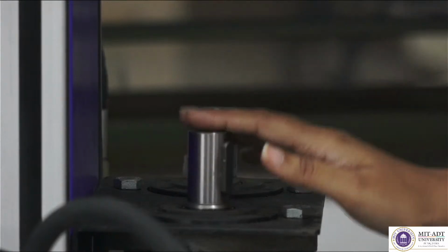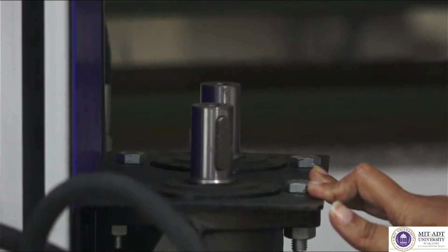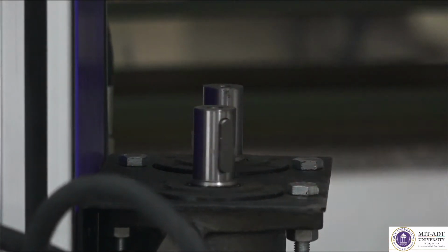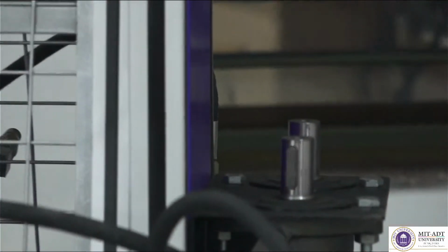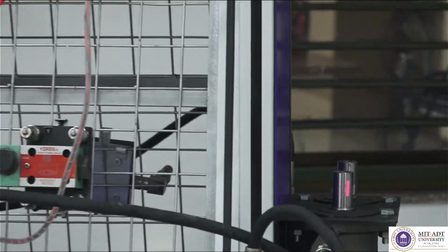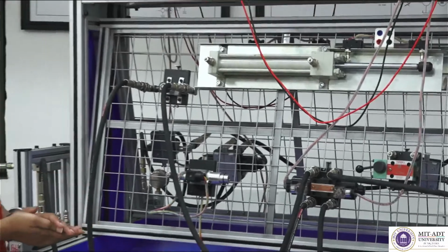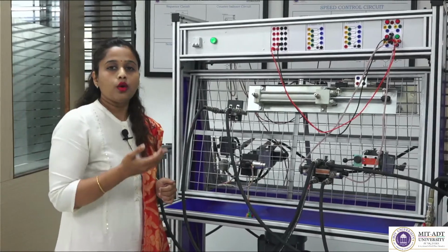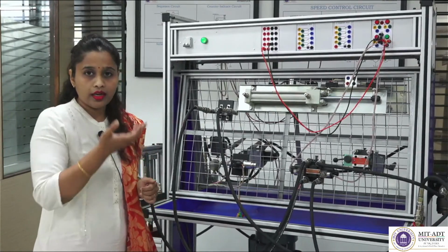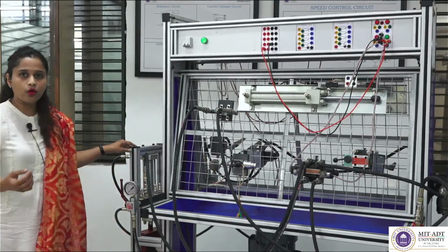Okay. So, this is how this hydraulic motor or an angular actuator is going to show its performance with the help of electro-hydraulic system. It is majorly used in case of the hydraulic drilling machines or wherever we require a rotary motion. Now, quickly let us see one more hydraulic circuit which is nothing but based on lowering a very heavy load in vertically downward direction. So, I need to just wait for a moment.